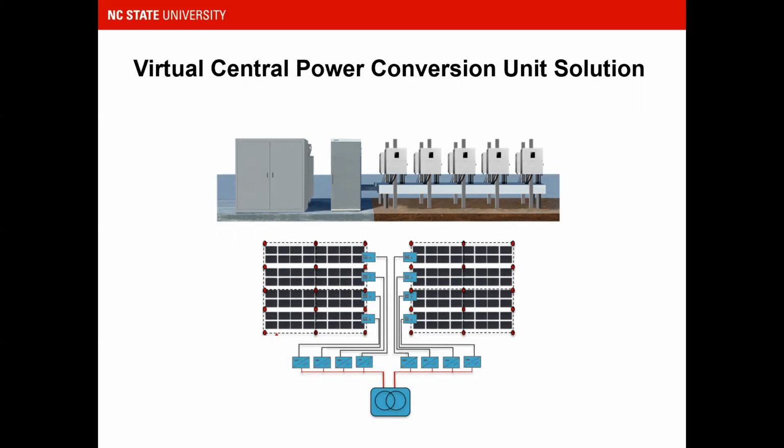with the distributed topology. So the virtual central skid solution relies on the string inverter technology, in which string inverters are installed all together close to the step-up transformer in a central block fashion. Like you can see here in the graphic, all the inverters are tied together and very close to the step-up transformer. So the AC cable between the inverter and the transformer can be reduced a lot. The main purpose of this product is to combine the benefits of the two above existing topologies.